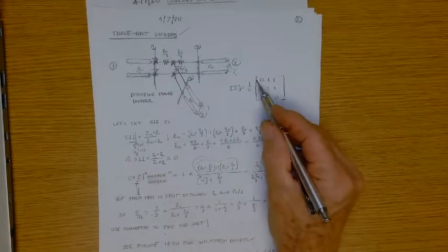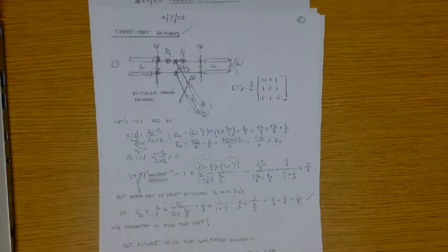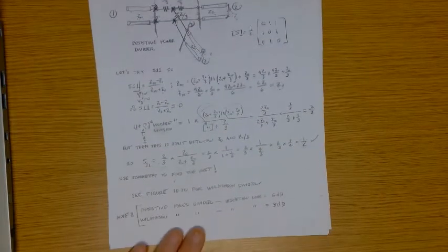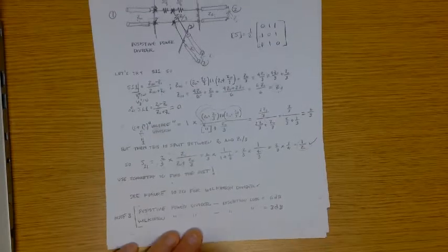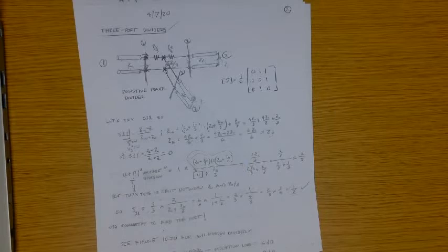And so again, going through the circuit analysis, we've proven that this indeed is the scattering matrix of that resistive power divider, right? So there's other power dividers. This is one manifestation of a power divider. If you look in the text, you've got the Wilkinson power divider and you've got the resistive power divider. He presents two different topologies to achieve a power division.